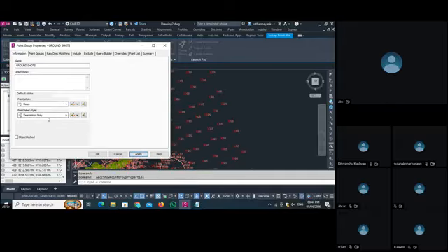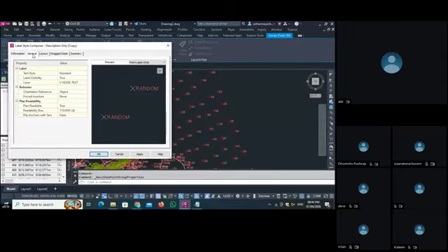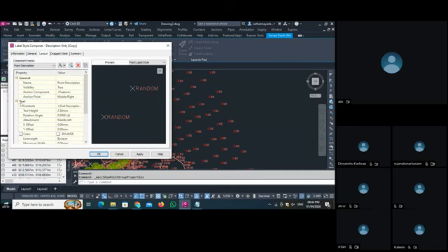Now you can edit this point label style also. If you go here and say edit current selection, but my suggestion is to first copy the current selection. Okay, then you edit this. Then you go to this tab, layout, and in layout you can go here to text.